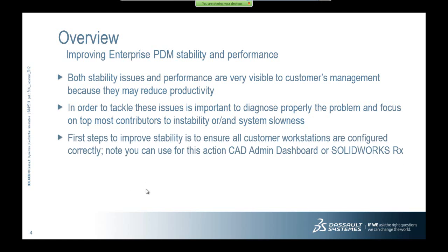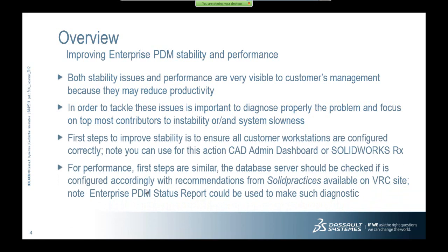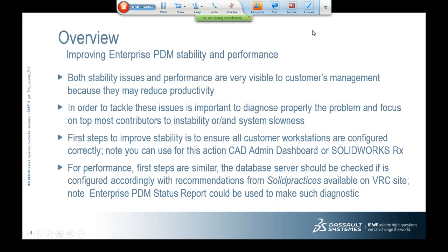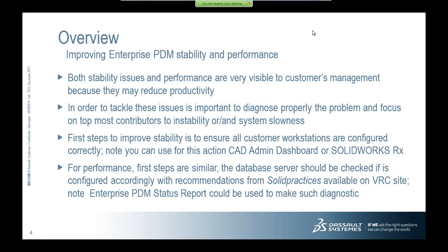What are the first steps when we are dealing with such issues? First of all, for stability, you can run a diagnostic tool such as SolidWorks RX, and keep in mind that it is available for our customers and also for resellers. There is also a new functionality, the CAD admin dashboard, on the customer portal, that should give you an overview for a given serial number of all the machine environments, if they are using supported drivers and so on.